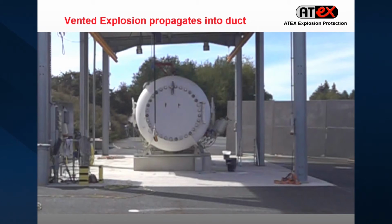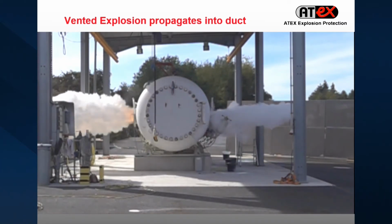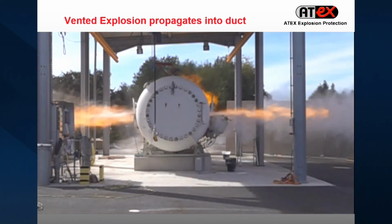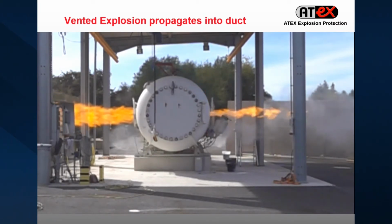What you can see now is we have two small openings, which could be ducts going into the vessel, and on the other side we have the explosion that we have already seen before. This is a slow motion high-speed video, and you see that a little cloud comes out, and then we ignite, and the explosion will go into the ducts, which we have taken away, and it will be vented to the outside. But just look at the force, how it is pressed into the two ducts. With high speed they press the explosion into the duct, and then it continues to accelerate in the duct.